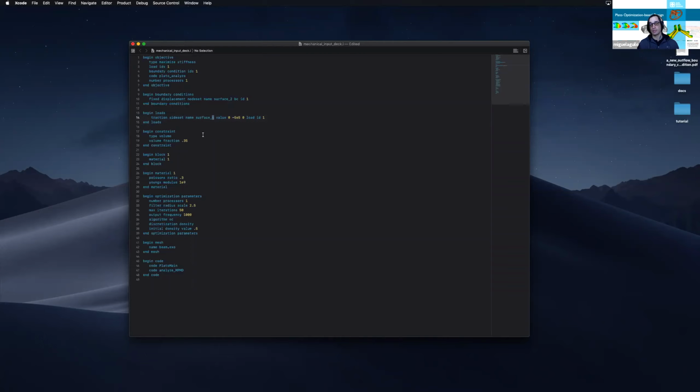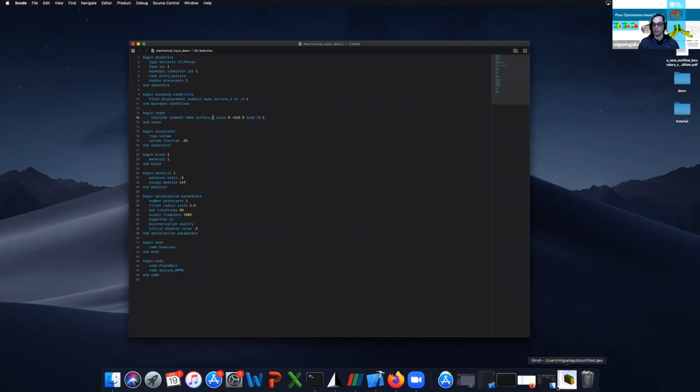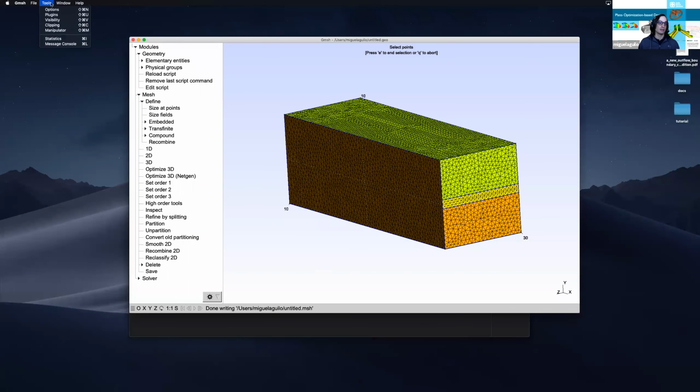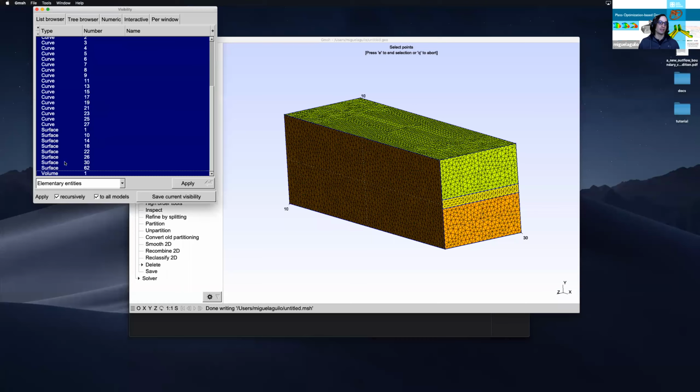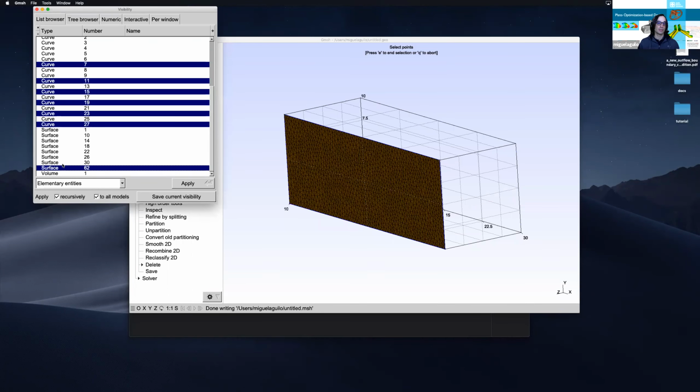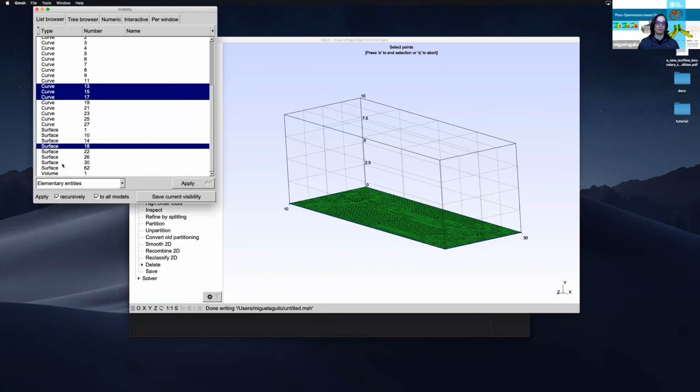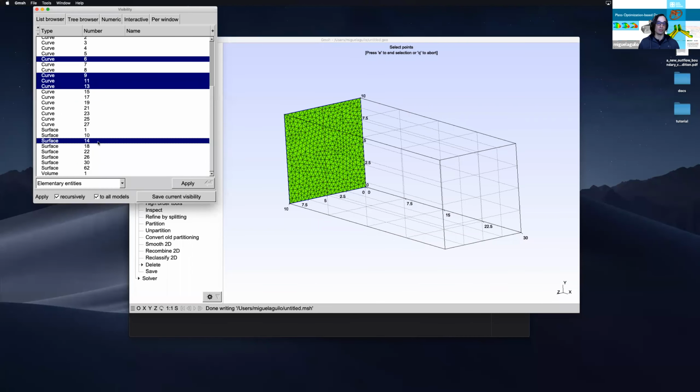If we're using Gmsh, when Plato does the translation, it assigns surface_6 to this face here. Actually, I created it in a different order, but in the model that I'm running, the name that the surface was given was surface 6. For this model, it will be surface 2. But in my model, it was 6.